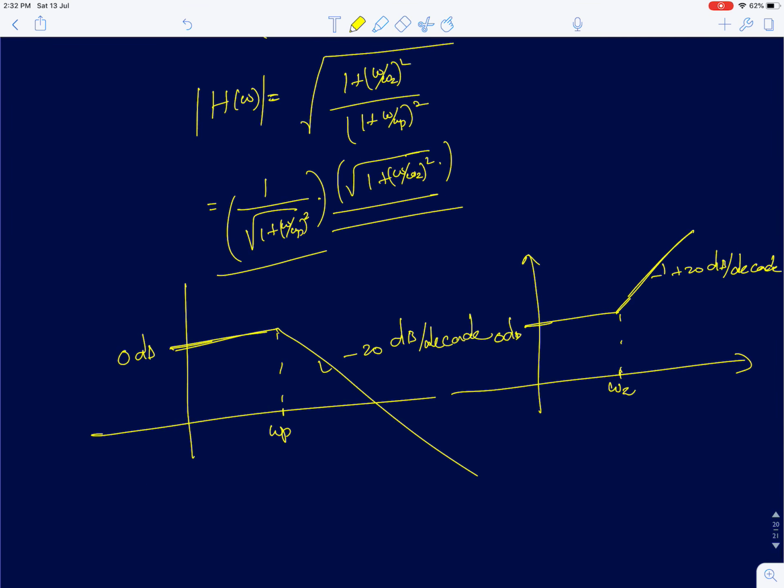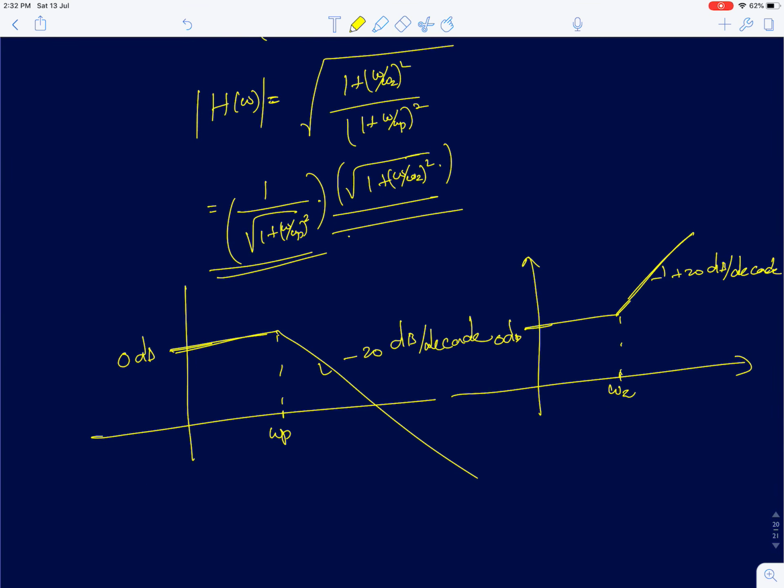Okay. Now when I multiply two functions in the normal domain, and I take logarithms of it, multiplications become additions. That is one other reason why we go for logarithms, because multiplications become additions and divisions become subtractions. In most engineering systems, in circuit systems, we encounter cascades of systems, so the gains get multiplied. By going for logarithms, those gains can simply be added. That's one other main reason for resorting to Bode plots, or taking logarithms of the gains.